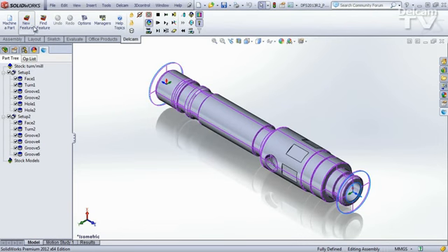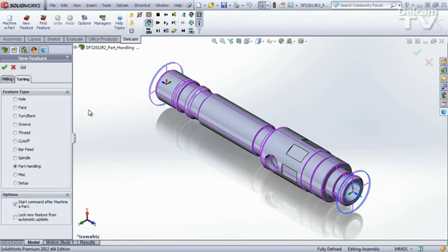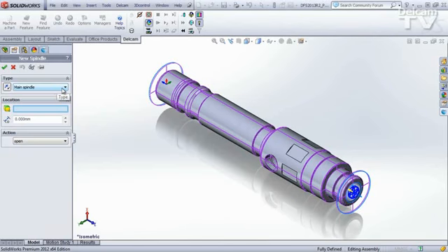The old way was to go to New Feature under Turning. This is a turn mill part, so under Turning we'd have to go to Spindle, and you had a couple choices in here. If your post supported it, you could go to a custom transfer and just select the one you wanted. If not, though, you'd have to go either to main or sub spindle and program each function one at a time. So each function, opening the jaws, closing the jaws, positioning the sub, each one of those functions was its own feature. So you had a lot of features and there was a lot of potential for errors.